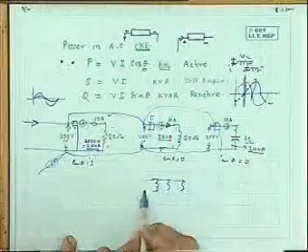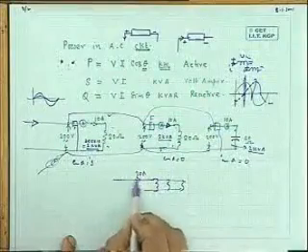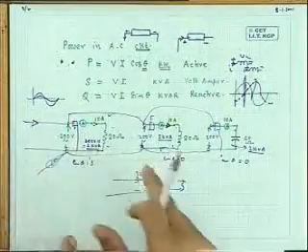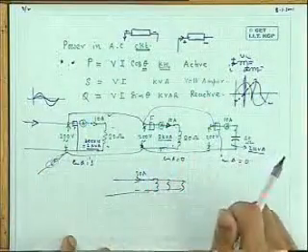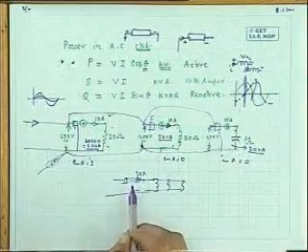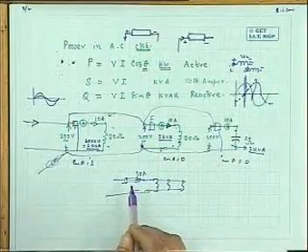If your consumers all have connected inductive load, let us assume 20 ohm, each one will carry 10 ampere. So 30 ampere has to be carried by the conductors connected between the generating station and these consumers, and the conductor cross section will be higher.